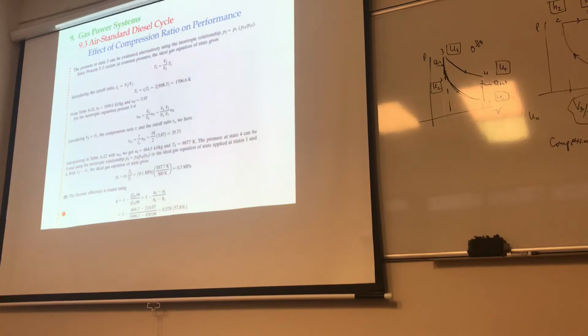The last part is really just another isentropic process, done essentially the same way as between the other states. Between 3 and 4, this is isentropic. So you do the same thing with the VR, same methodology, same ideal equation of state. Now you read that last value, which is U4, from table A22. Up to this point, you have all the states defined, all the temperatures, the pressures, the U's and the H's where need be.